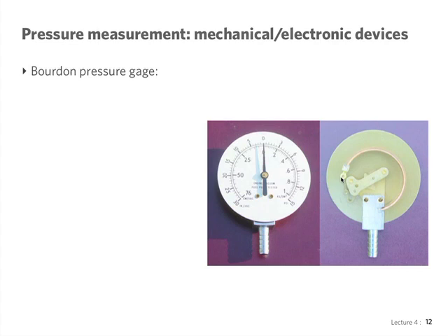This hollow curved tube is connected on one side to the pressure that is being measured. This pressure comes inside the tube, and you can imagine that if we put more pressure, it's like those old birthday things that you blow into, and they straighten up.